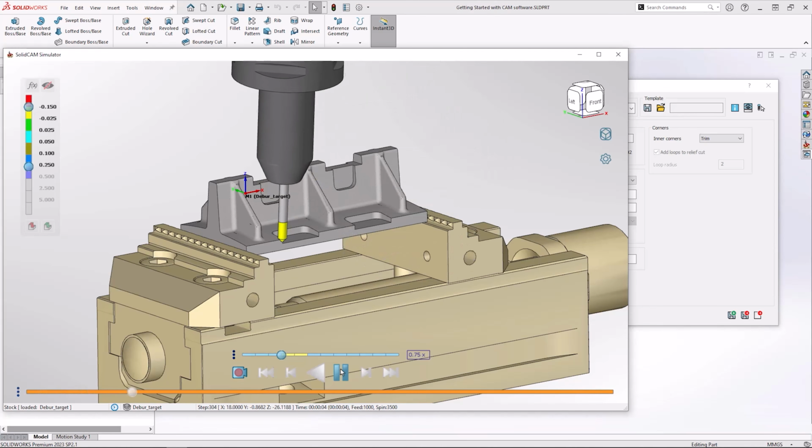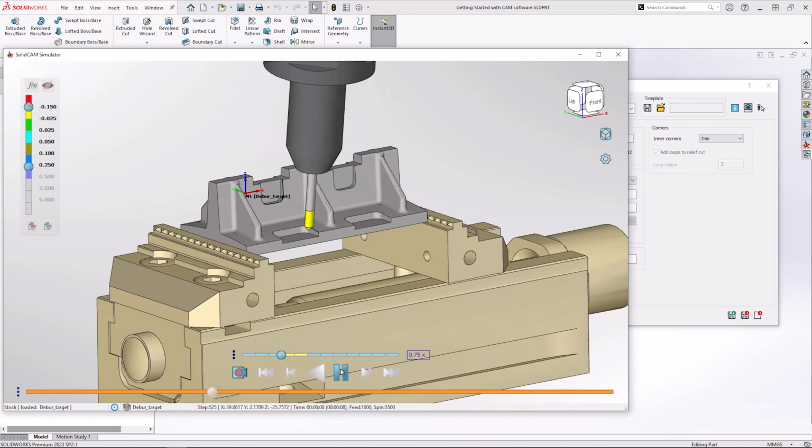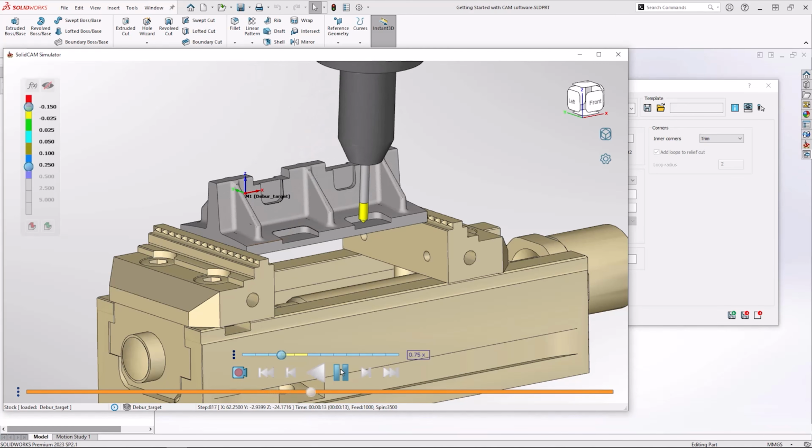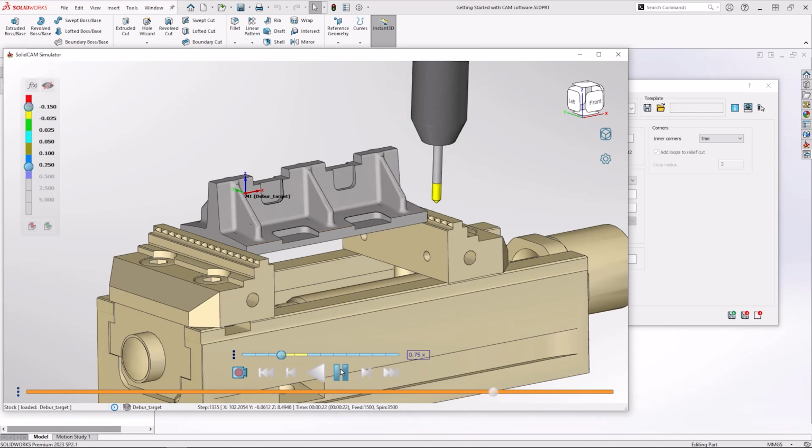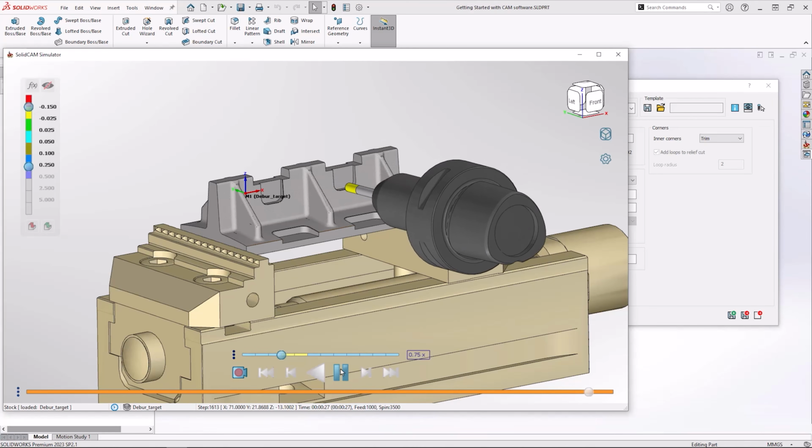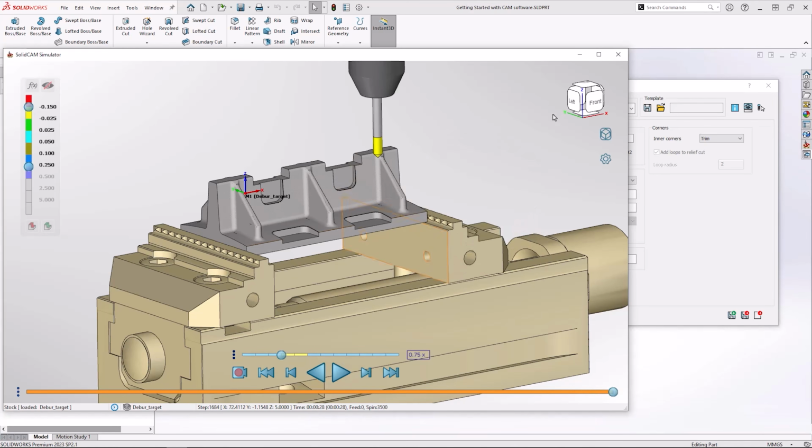Reviewing the toolpath created, we can see the tilt and the rotary of the tool is quite different. This all takes into account the differences we have in the tool geometry, moving from a ball nose cutter to a chamfer mill. What it will mean though is we still get the chamfer that we require upon our part to make sure we've machined it absolutely as we expect it.